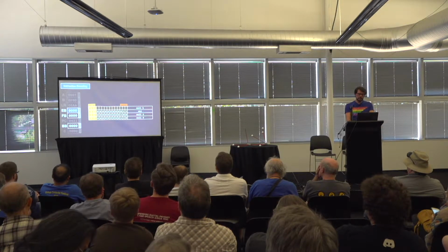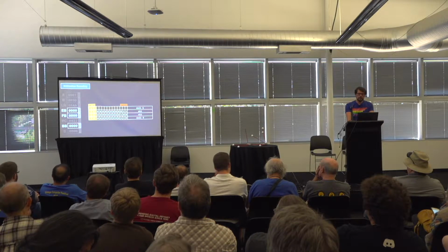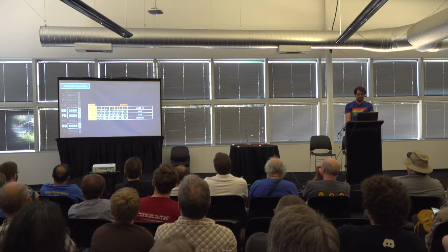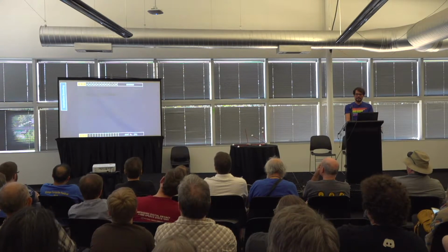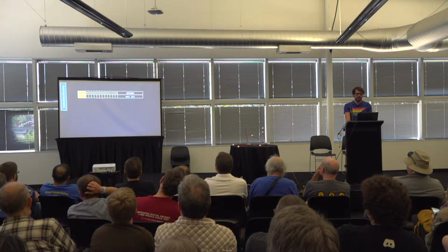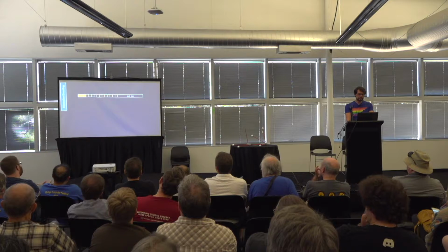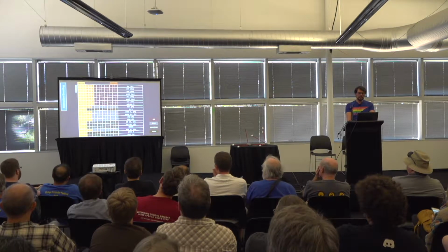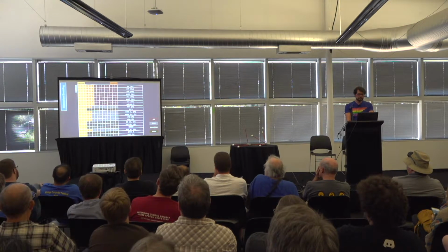Since jumps to the bank register don't make sense, these codes are used to encode STI, CLI, and extend. Extend is a prefix. It changes the meaning of the opcode of the next instruction, allowing for this second set of 2-word instructions.